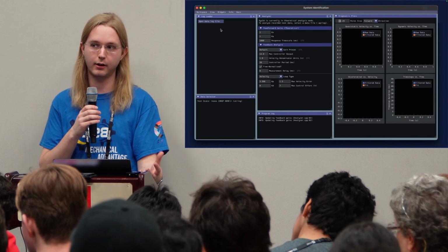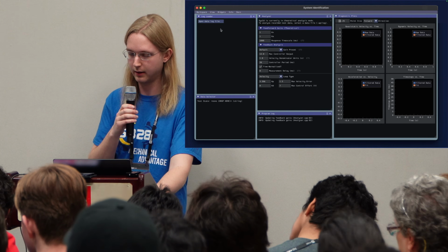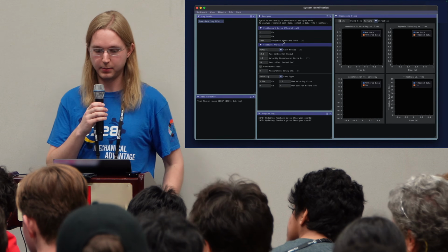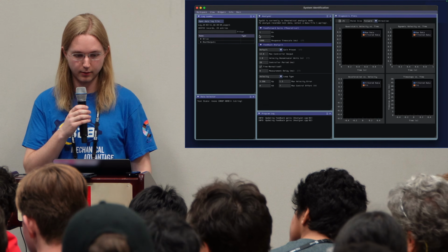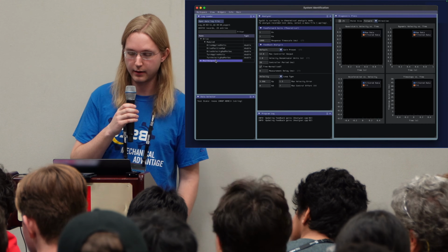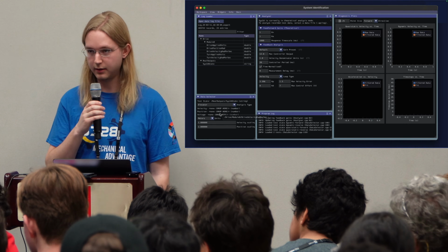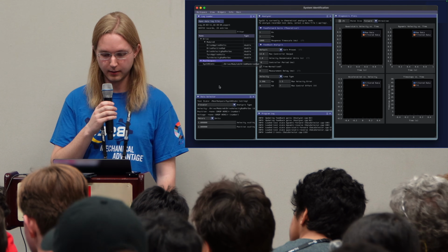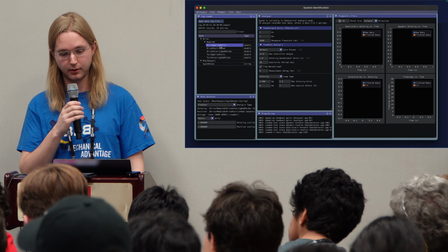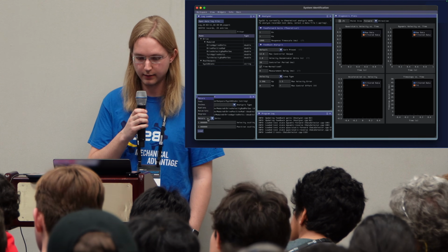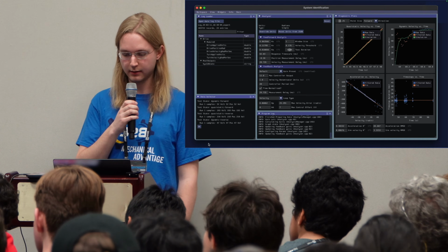This is calculating the actual values of Ks, Kv, and Ka based on all that data. What we're going to do is open up WPILib SysId Analyzer, grab our log file from the robot, and then we just have to select the fields for the test state, the velocity, position, and the voltage data. We also are going to, in a moment, select the mechanism type and the units, and then we just click the button to run the analysis.